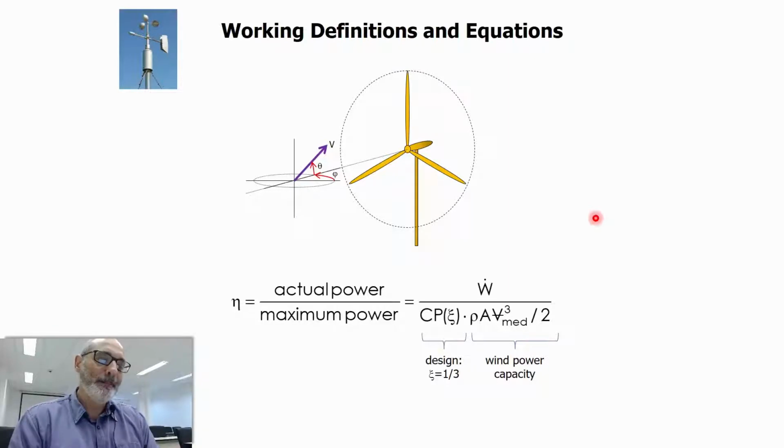How can you assess the capacity factor? Because capacity factor, as I mentioned, is related to the intermittency of the wind. But when I say intermittency, it expresses an idea that things are changing over time. But what is changing? You have several aspects of the wind that can change and that can affect the generation of electricity. The intensity of the wind speed may vary, so the length of this vector here may vary, but also the direction from which the wind is coming may vary in time.